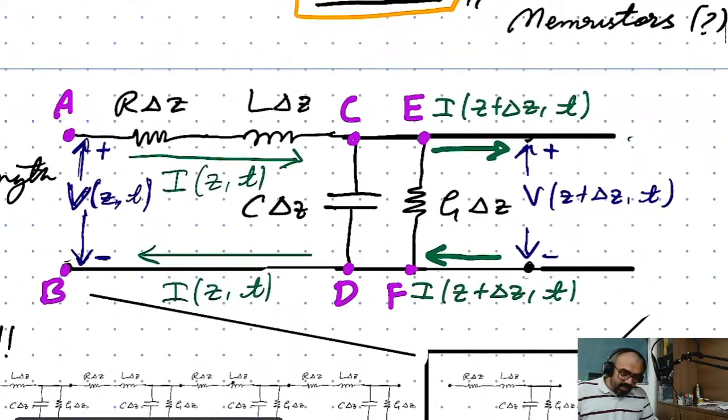And I want to also point out that the inductance and all these components that we assign to that little portion of transmission line are expressed as R times the length. So the RLGC parameters that we see here are per unit length quantities.